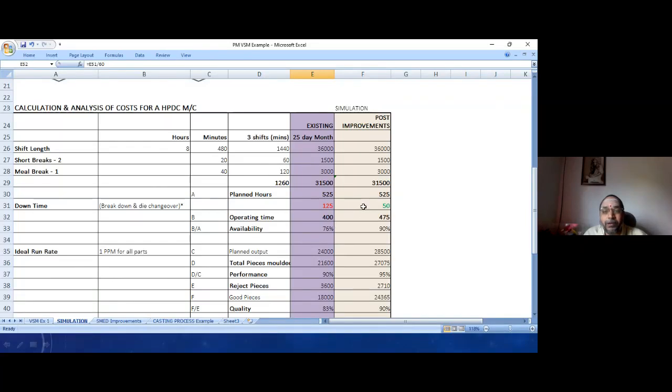But if you actually break it down at activity level, right, a number of insights you can have. For example, which product has higher batch volume and fewer changeovers? Which product has more changeovers but low batch volume? Which product takes more time in setting up, in changeover itself? No, which one will I focus on? That product with a higher time and a lower batch quantity. That is what I should focus on for reducing changeover, right? The cost of changeover. That is one insight.